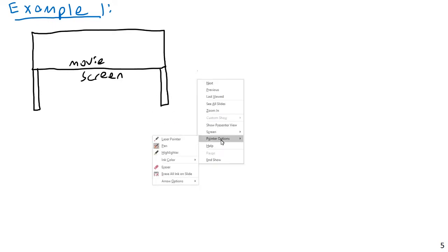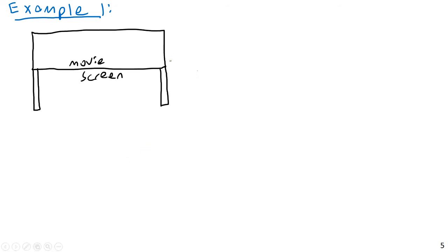And that's not going to be important, because that would be important if this were a civil engineering class and I was asking you to calculate that. There are actual tools you can use, such as ASCE 7, to directly predict the maximum velocity you'll have to design for based on height, the surrounding area, what area of the country, and things like that. But we'll keep it very simple here, and I'll just give you the velocity. So here, let's say the height of this is 20 feet, and the length is 70 feet.